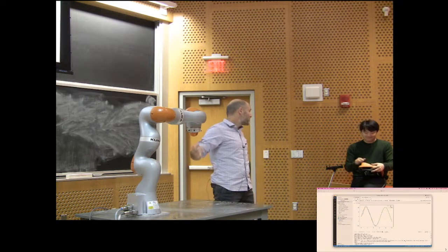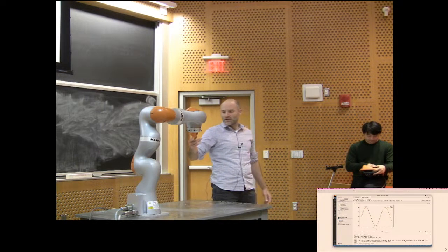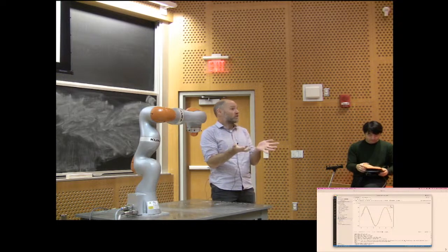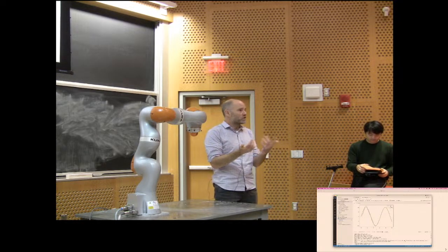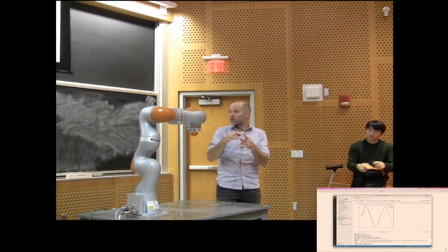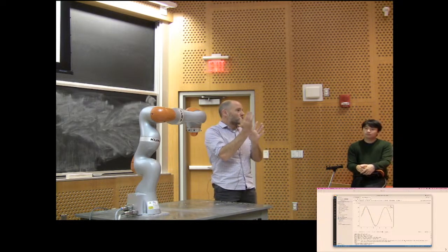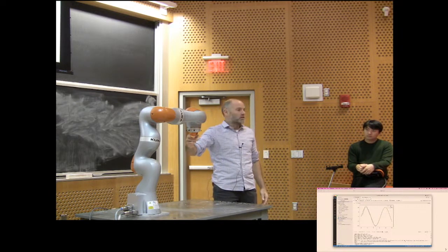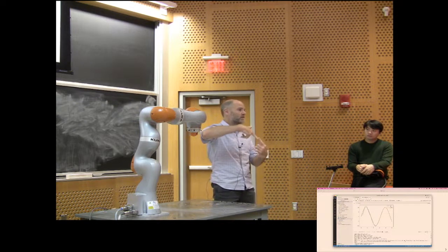Okay, and then we can do the same thing in rotational coordinates. All the same things work if you use our spatial vector notation and say that the thing I'm trying to control is not the position, but the orientation, or in general, spatial velocities and frames in the end effector. Then you can put a stiffness. You have to be a little careful at how you write stiffness in 6.